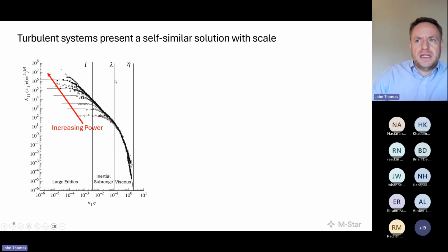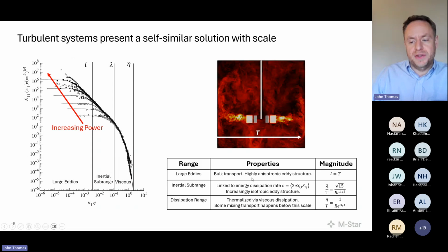Likewise, the Taylor scale links directly to the Reynolds number. The integral scale will be a function of topology, as it were, but those are the things we're going to resolve the best explicitly. It's here we're concerned about as the grid size gets bigger, but importantly, because this grid size scales with length scale, we can achieve a practical LES simulation, even at large scales.